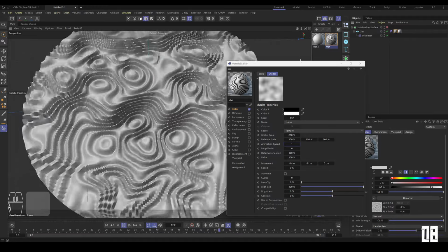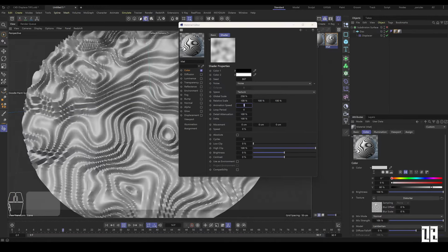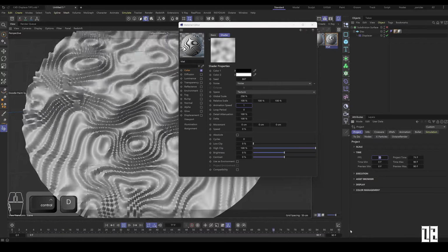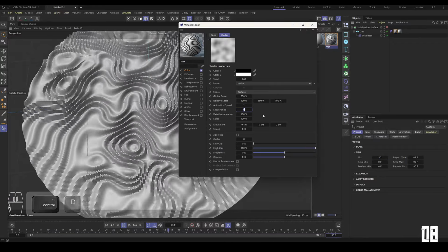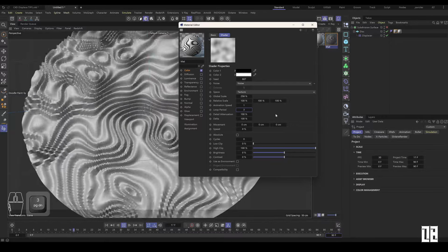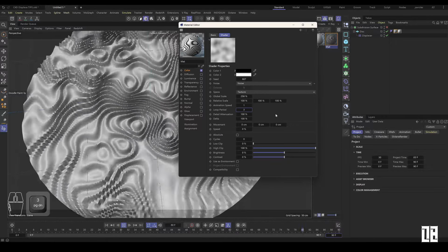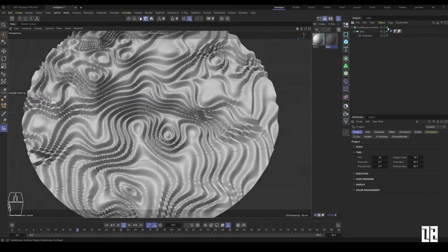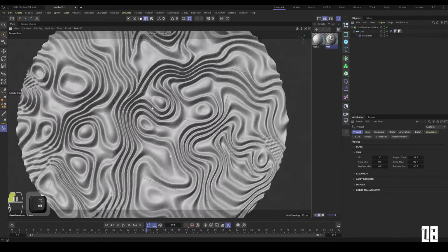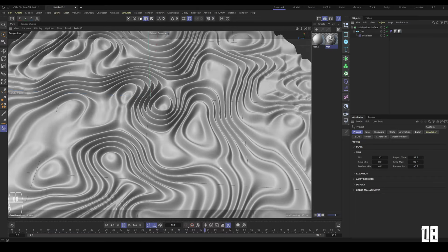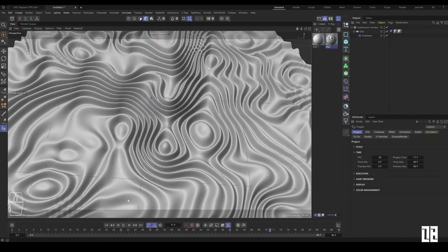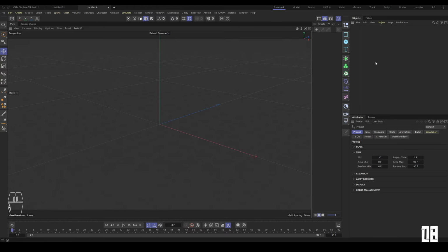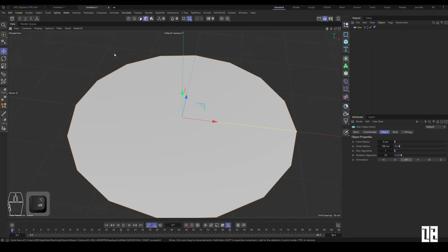The project is set to 30 frames per second, and the total duration is 90 frames, which is 3 seconds. Then enter 3 for the loop point parameter. Now you can see that the animation loops seamlessly. These are the techniques that entry-level C4D users might use. Next, I will explain some of my own ideas, just for reference.